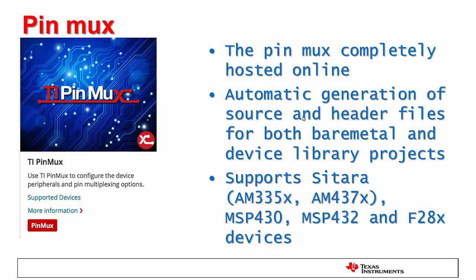Several microcontrollers and processors assign more than one function per physical pin on the device. The Pinmux is the utility that helps you configure which pins will be used by the peripherals you need. And, just like the standalone version, it manages pin conflicts and generates source code automatically. The current version supports Sitara, MSP430, MSP432, and some of the latest F28x devices.